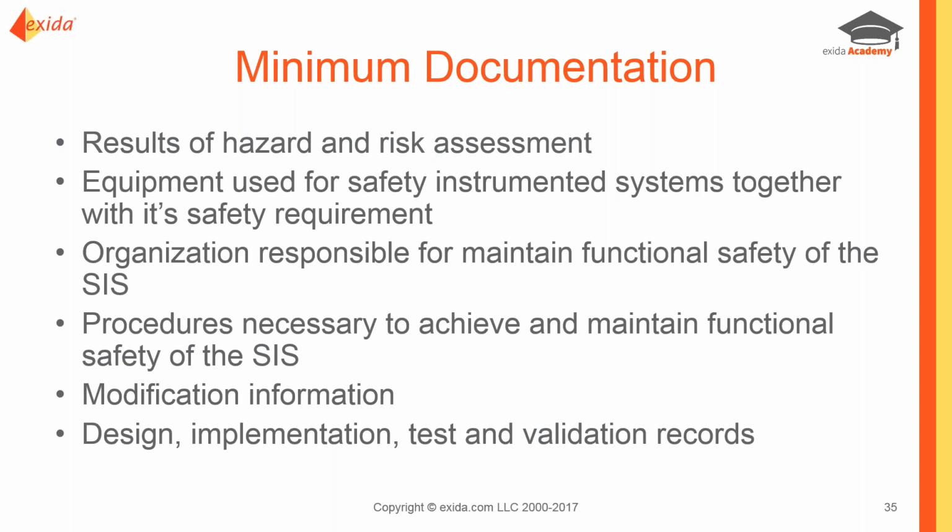Some of the minimum documentation, these are specifically identified within the standards. Obviously, the results of the hazards and risk assessment, that first step in the block. What equipment did we use? So we should expect specifications on all the sensors and the final elements associated with any kind of safety function on the logic solver.